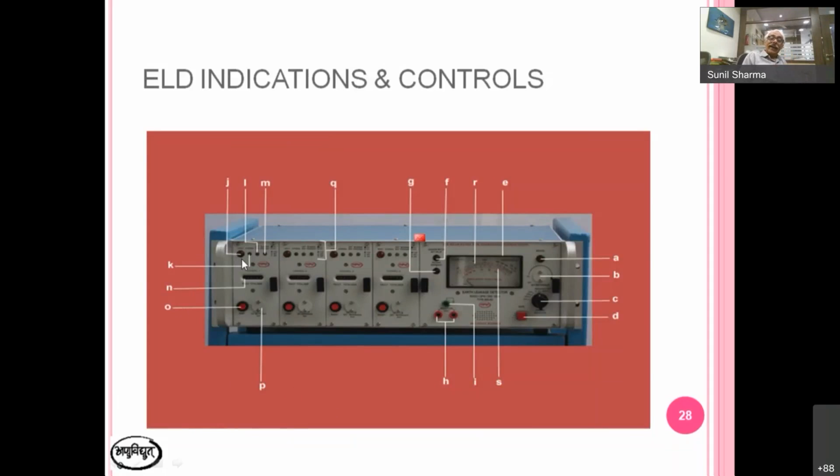These red and green, this big red and small green, are like your signals, red signal and green signal. One of these remains on, either red or green. In any case, if red is not on and green is not on, the channel is faulty or switched off. So one LED should be on.